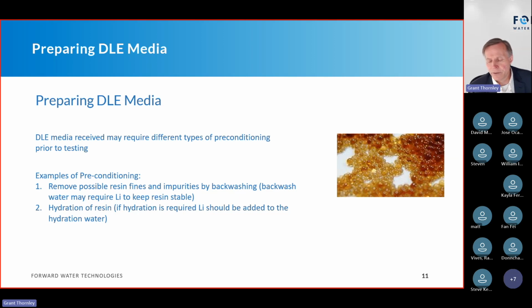As I said, I've seen one run through that didn't do pre-treatment, and the lithium levels are too high. It looks great, but that's because it wasn't washed. The other thing is you might have fines. You want to precondition by backwashing, like a typical ion exchange resin, to backwash the fines.